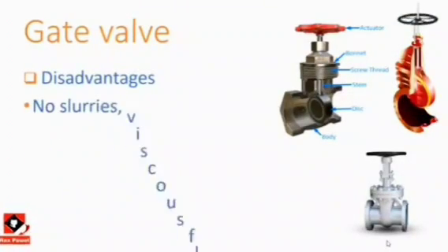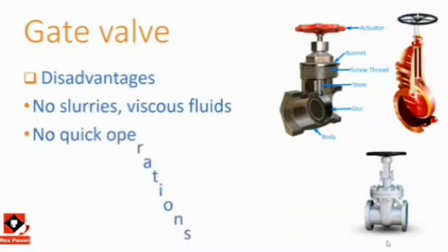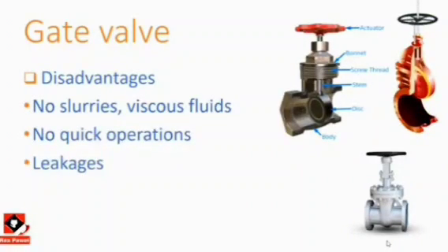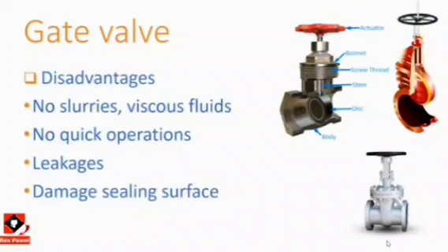Disadvantages. A gate valve cannot deal with slurries or viscous fluids and cannot operate quickly. Sometimes leakages may occur due to load, and sealing surfaces get damaged due to friction.